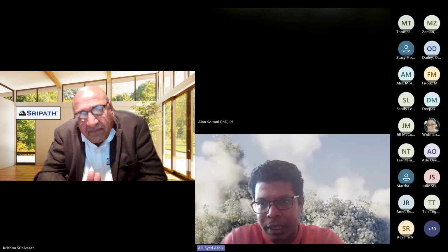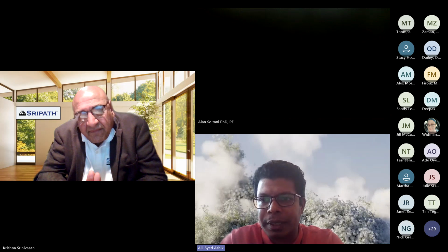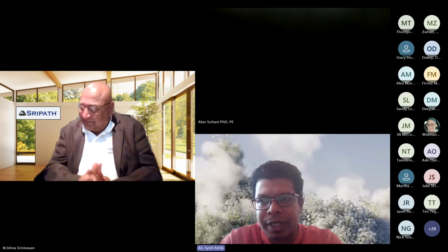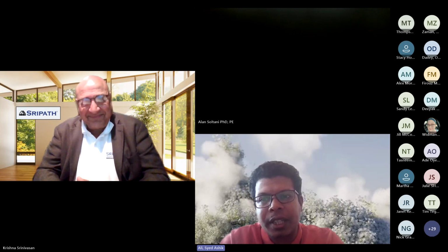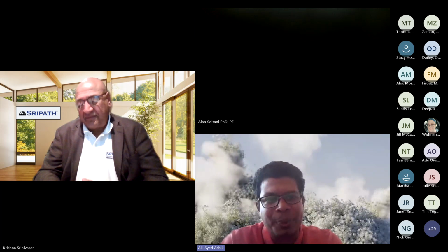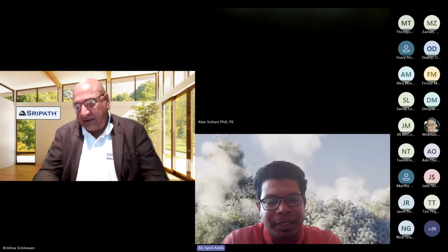The next question is, how will the rejuvenator interact with the SARA fraction? Can we expect the same proportions as in virgin binders after rejuvenation? Some studies have reported an increase in oxidized functional groups in rejuvenated binders. Could this pose a long-term durability concern?